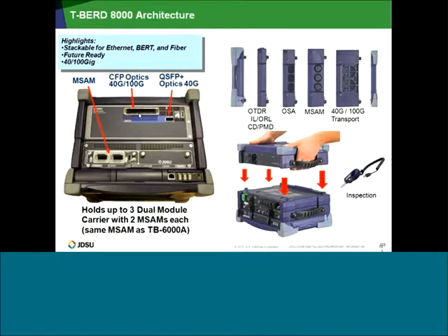A lot of people didn't know this, I found out, but there's a certain number of insertions that you can do with the optics, especially for CFP 100 gig optics. There's a finite number of times that you can remove and then insert that. So one of the good things is that since you have the QSFP+ and the CFP, you don't have to remove or insert that many times. Of course, we also recommend, there is also a finite number of times for XFPs and SFPs, but not as delicate as a CFP, for example.